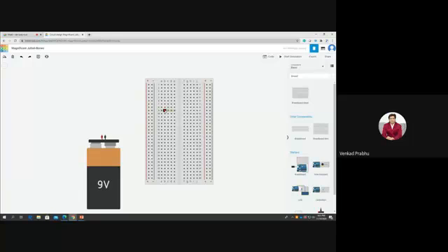But if you move your mouse to the inner part of the breadboard, you can see the selection is row wise. That is what is labeled there: first row, second row, third row, fourth row, fifth, like that. This small breadboard has 30 rows. So if you want to place the devices inside, you have to choose row wise for each feature. And if you want to fix it in the outer part, it is going to act column wise. We will see both scenarios one by one.